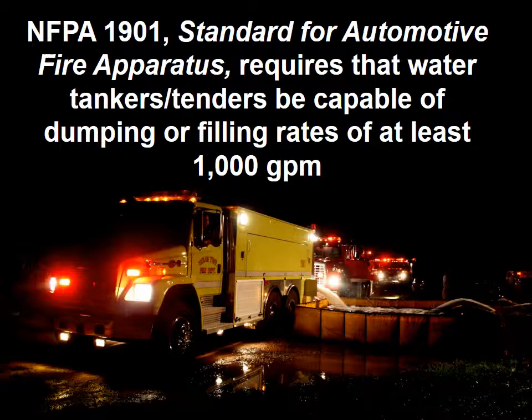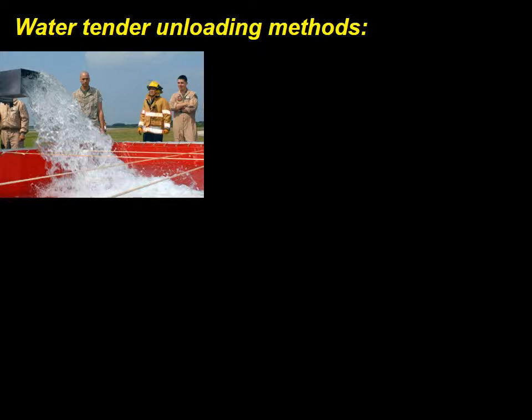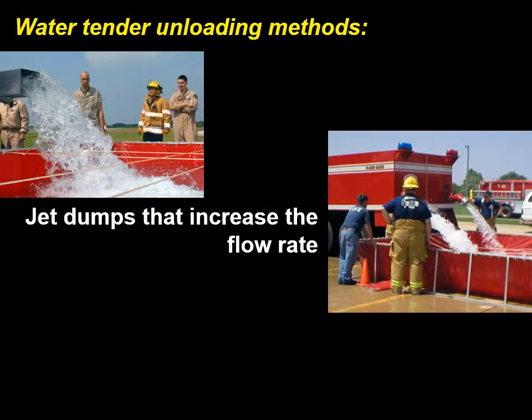Water tenders or tankers are covered under the NFPA 1901 standard for automotive fire apparatus, which requires that water tenders on ground level be capable of dumping or filling rates of at least 1,000 gallons a minute. Water tender unloading methods include gravity dumping through large 10 to 12 inch dump valves, jet dumps that increase the flow rate, apparatus-mounted pumps that offload water, and any combination of these methods.